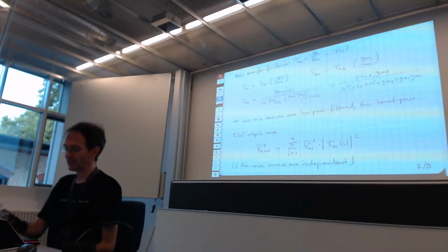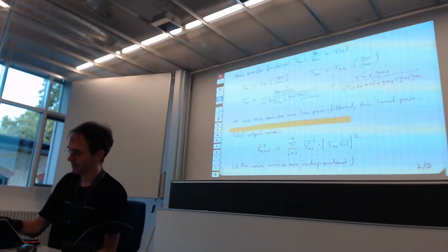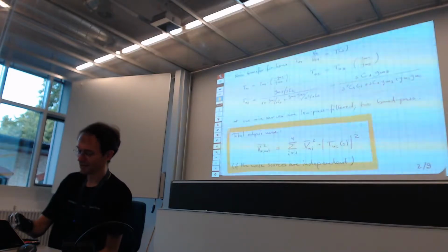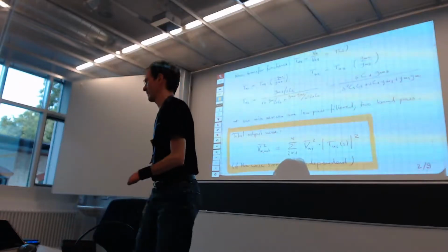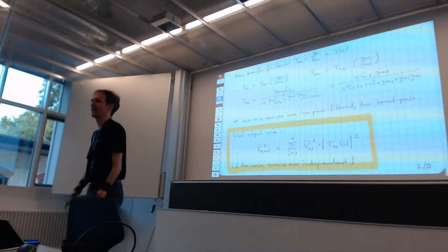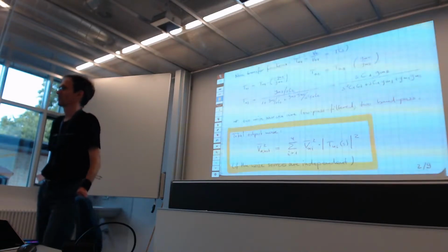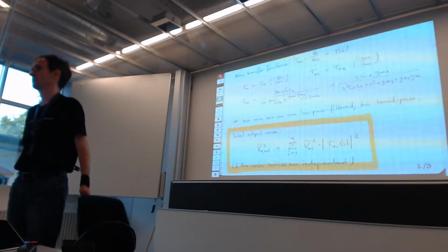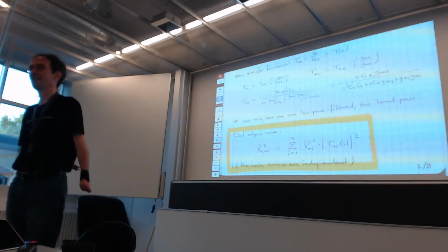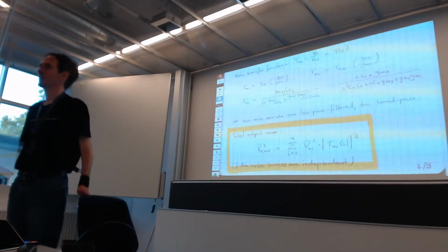And really, it's quite funny to take a formula like this and evaluate it. Because sometimes, if you do that, you even find errors in datasheets of op-amps. So there is one example. I don't know whether I can find it again, in a datasheet of Analog Devices, where they give you the budget of the total noise coming out of the circuit in table form, and the number is wrong. You can very easily test that now if you know this simple noise addition formula.